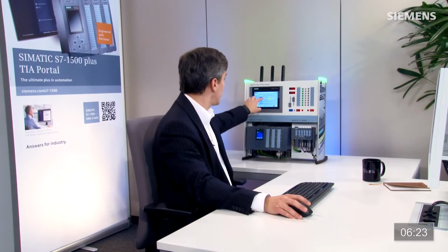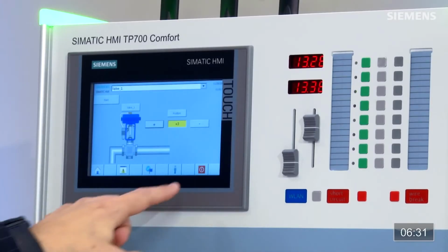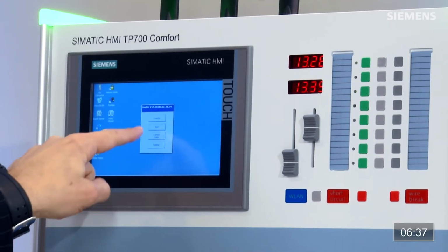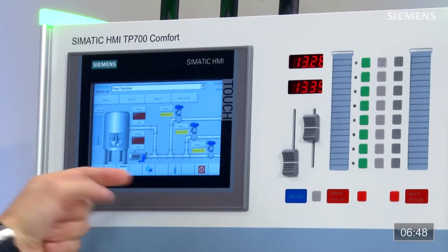However, I still have complete control from the panel because I have an existing connection. Until I reestablish connection, does it actually blow it up? Well, let me actually shut down the runtime. That's the easiest way for me to do this. Once the runtime is completely shut down, it'll give us the ability to restart. Once I do restart, it's actually going to try to reconnect to a protected CPU at Level 4. However, you'll see quite instantly we get all hash marks on these bit fields.